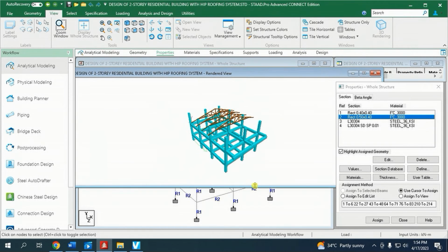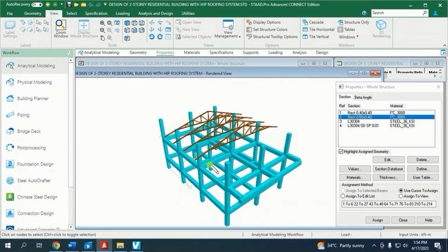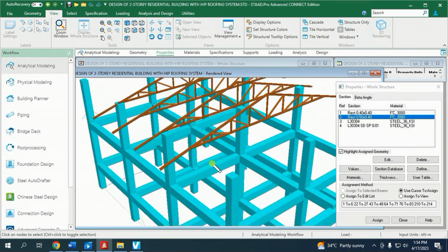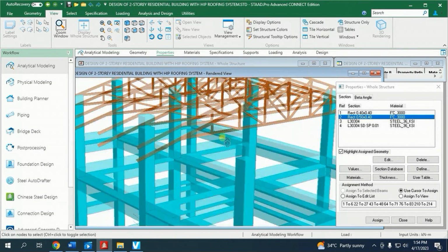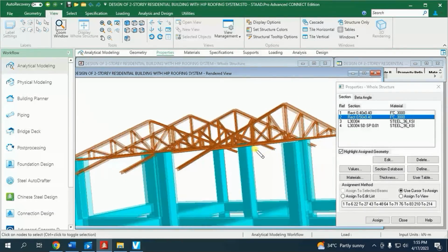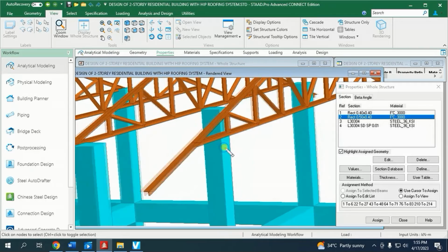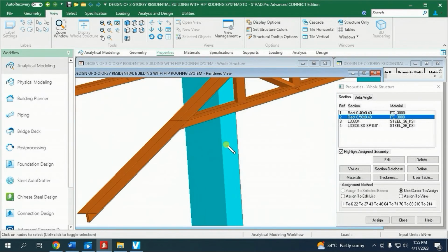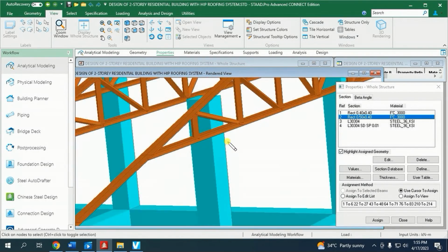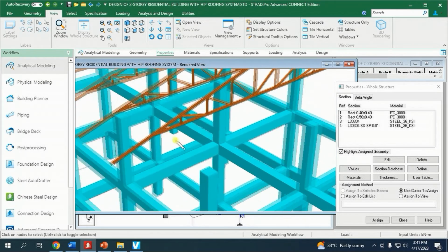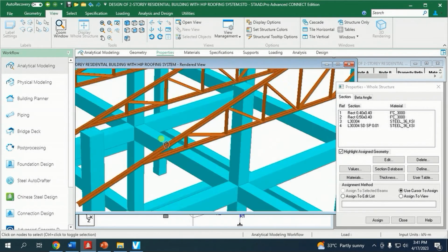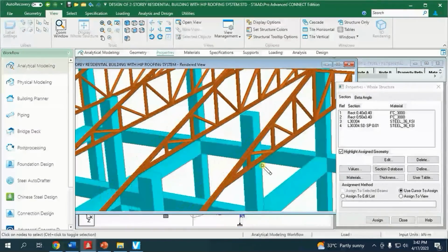So here, in the bottom chord of the truss, the angle bar is not oriented correctly. It is currently facing downward. Look at it closely. In this case, we can reverse this orientation by rotating it to an angle of 180 degrees.